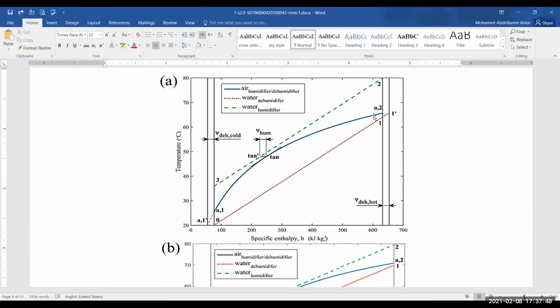So the expressions that we used to write for humidifier effectiveness is not really accurate in that sense. And we need to come up with another expression. Actually, for a few years we have been after this issue, and probably you have seen some of our earlier work showing performance of the unit with a dotted line that shows a violation of the second law of thermodynamics.